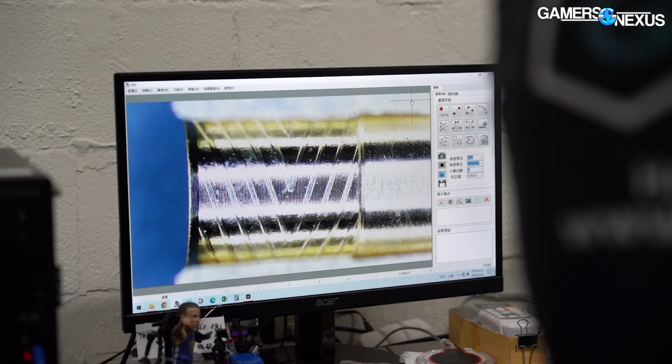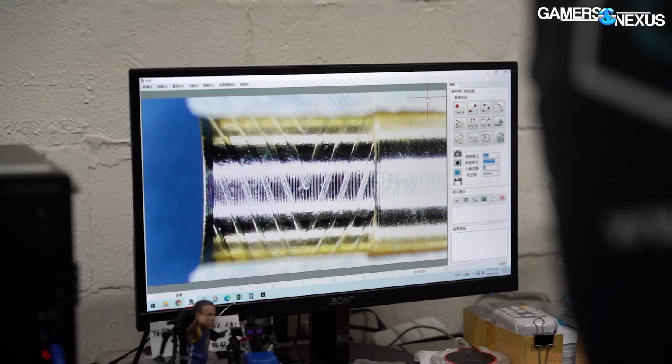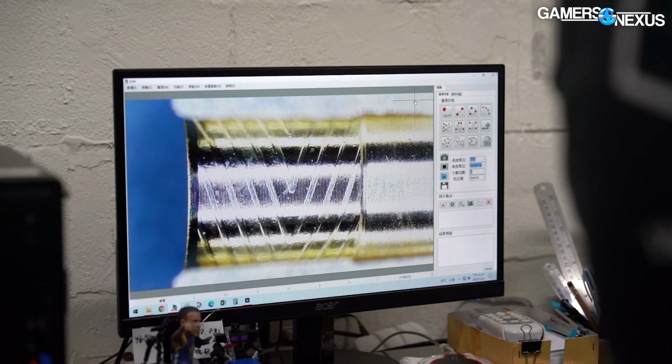But the question is, what benefit do you get out of them in fans? And I would argue that it's not as simple as looking at them and saying, oh, they have grooves, so they must be better, right? Of course, the grooves enhance fluid circulation and pressure build up. But the question you should ask is, does your application require that? Does your application benefit from that?